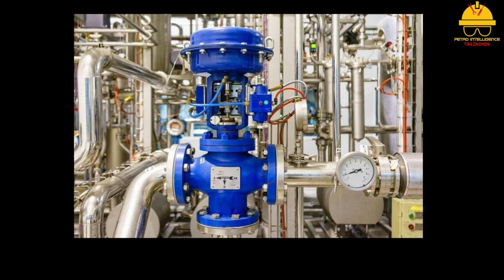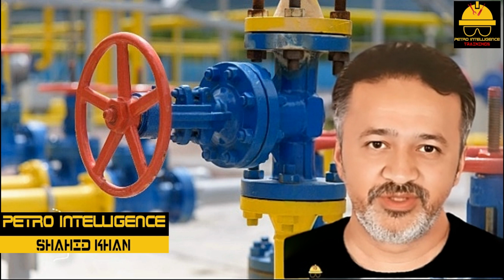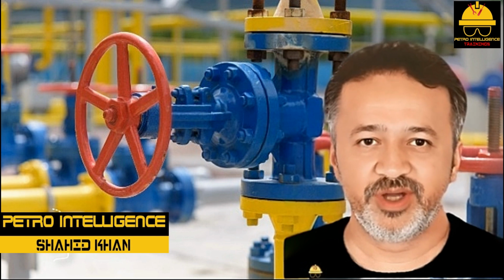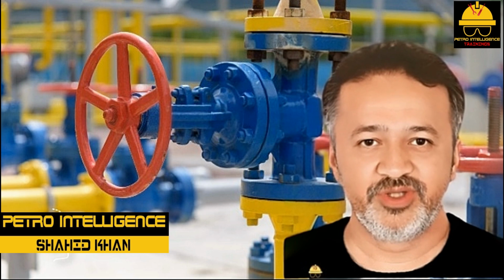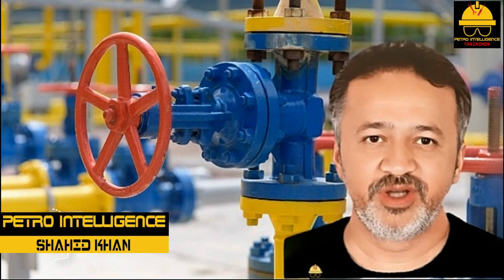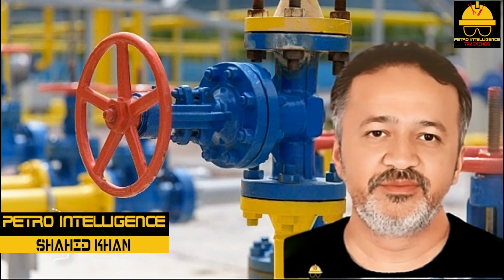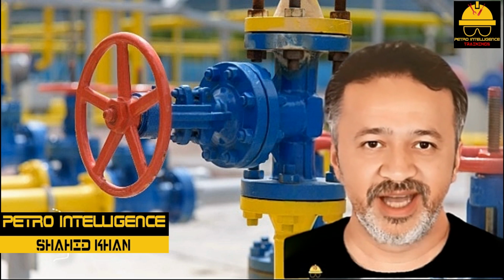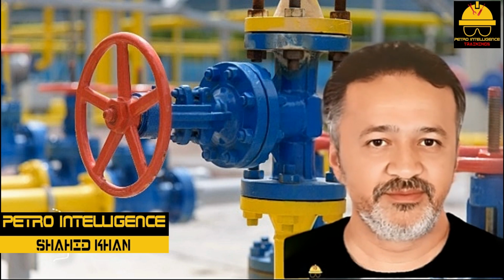The most common type of automated valve is a globe valve because of its versatile on-off or throttling capability. Control loops use on-off or throttling type valves to regulate the flow of fluid into and out of a system. Automatic valves can be used to control pressure, temperature, flow, or level. Automatic valves are categorized as either control valves or spring or weight-operated valves. Control valves can be air-operated, electrically operated, or hydraulically operated.